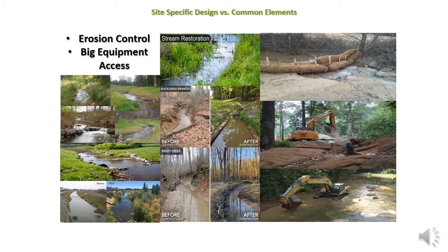You're going to end up stripping a lot of vegetation away to do this correctly. So the grubbing, part of the process of going in and removing vegetation, the cut and the fill, in some cases can be very severe. This is along an active water body. How do you control that? And so you'll see in a lot of these examples is tamping down erosion during construction, tamping down erosion in the long term. This is really what you're doing with stream restoration efforts.